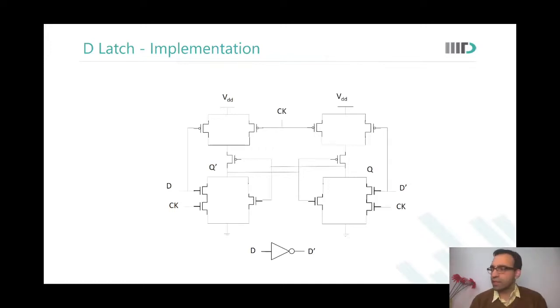Can you just quickly check if this is equivalent to the circuit that we saw earlier? We have used complex gates here, so it is 14 transistors. But we wanted a 6 transistor memory cell. This is the simplest clocked storage element we're talking about, but somehow everyone said SRAMs would have 6 transistor cells. So how do you reach 6 transistors?